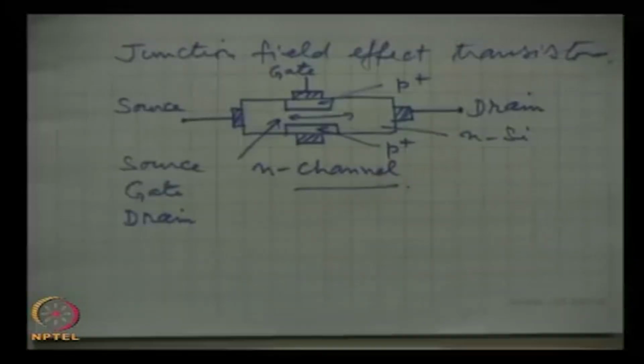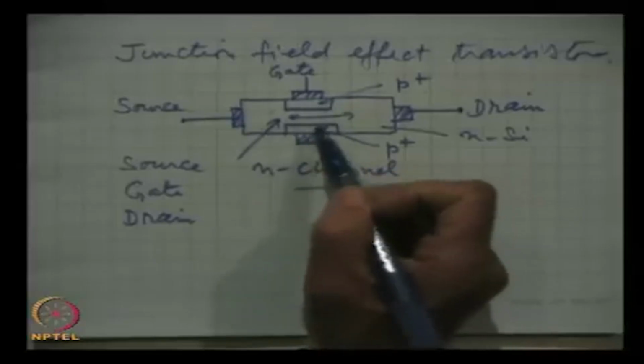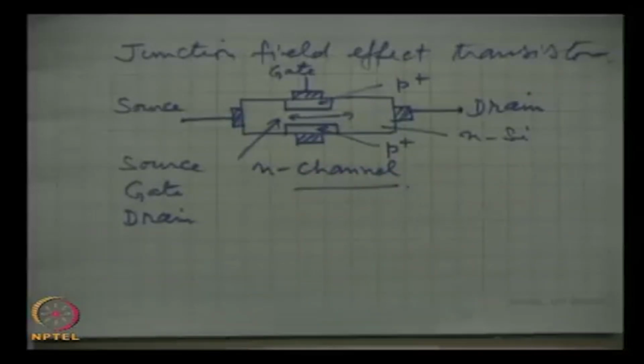What will happen when this is n type silicon, an n substrate over which we have grown two heavily doped p regions? For the reasons which we have discussed in the p-n junction, wherever n and p type semiconductors meet, that means if there is a structural continuity, then the natural processes which start from diffusion and are followed by drift, that means a depletion region will be formed.